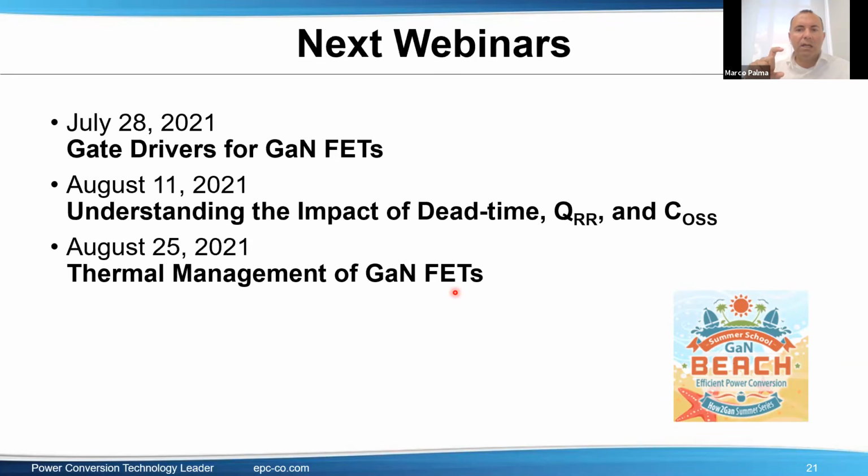They are made so you can then screw a heat sink on top of the device, and they have the exact distance you need so that the thermal interface material between the heatsink and the device has the right thickness. And that's the most efficient way to remove the heat. There are 3 ways to do it: passive air cooling with a heatsink, then you may have a forced air cooling with a heatsink, or you can have a heatsink with liquid cooling, depending on the application.